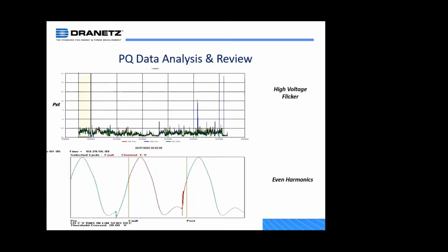And then these are various different things that you might be looking for. For example, flicker. If you're in a scenario where you have light flicker, then in post-analysis of the data, you look to see if the flicker exceeds the threshold at which most people will perceive, or witness, light flicker, and that is the Pst, perceptibility short term. Anytime it exceeds a value of 1, most people will witness light flicker.